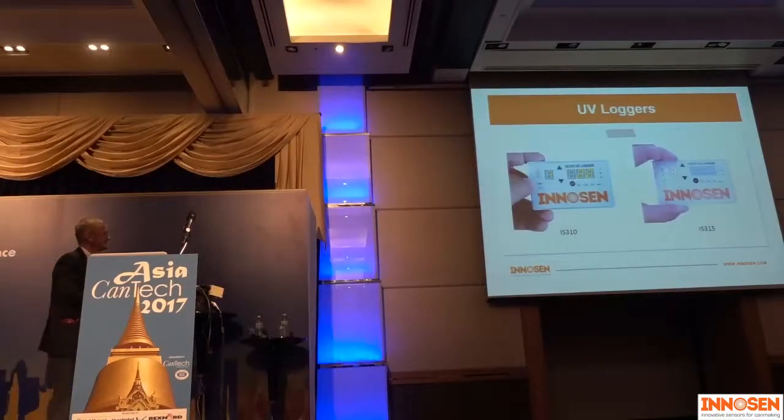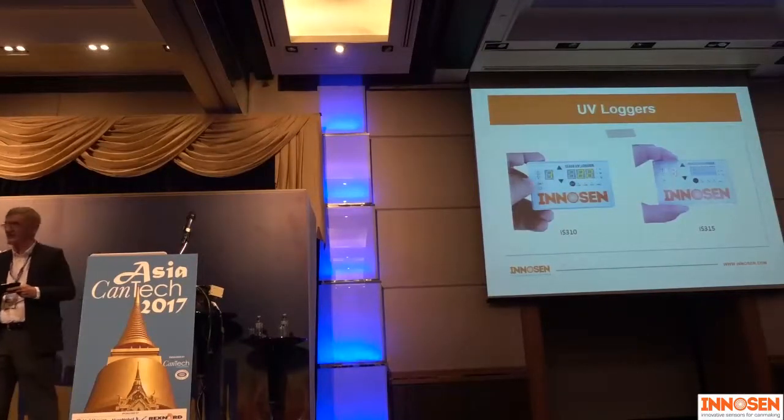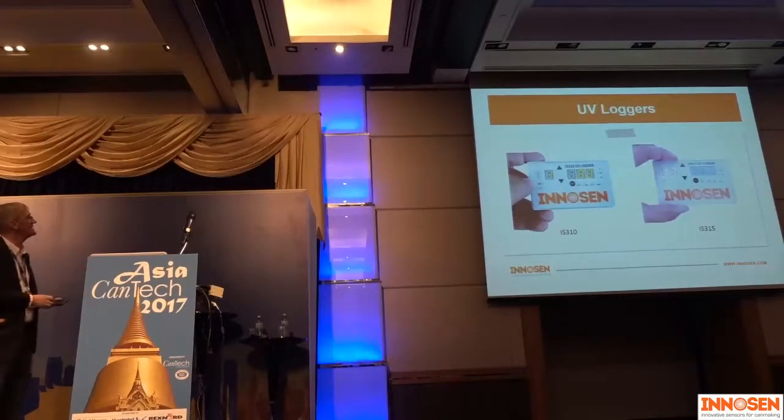UV logger. This is a measurement device we were showing at the booth. It is absolutely tiny. I have one here. Come and see me at the booth. It's the size of a credit card, 6 millimeters thick. You stick it on a sheet, it's got magnets, you feed it through your UV oven, and it records both the intensity and the power of each of your lamps. You can just store that on a PC and compare it to what it should be.